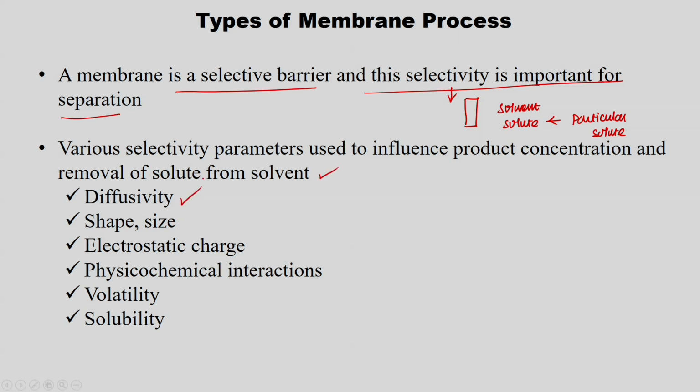So, one is diffusivity and the size and shape of the particles, because when we were discussing the different modules, we also said certain modules are not suitable for solutions containing particles, right. Certain modules need only a clear solution, right. So, size and shape of the particle is also important, and electrostatic charge, for example, if you are using electrodialysis. So, this is an important parameter to be considered, and physico-chemical interactions between the membrane and the feed.